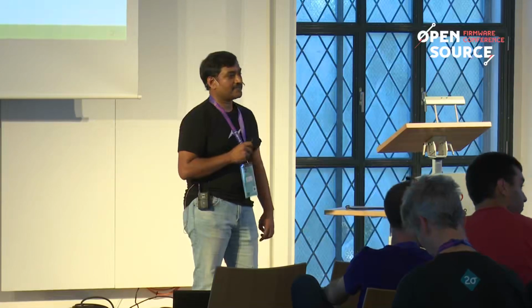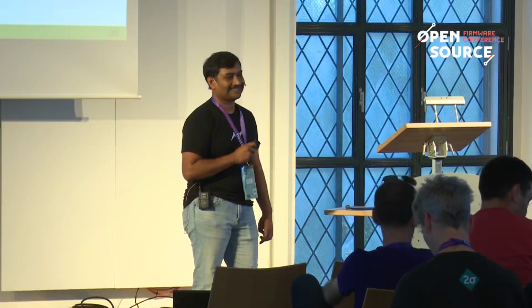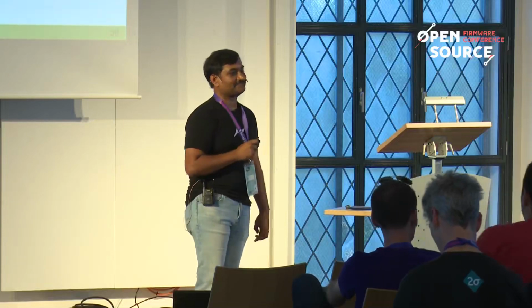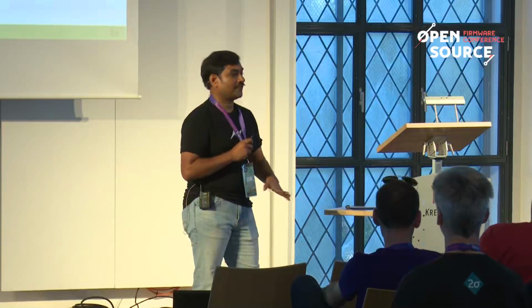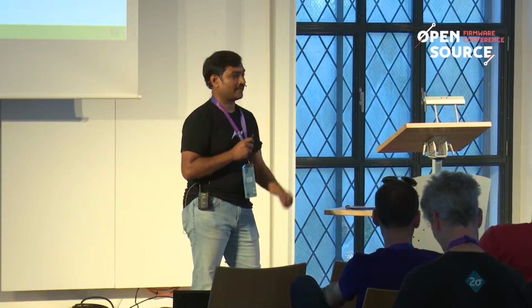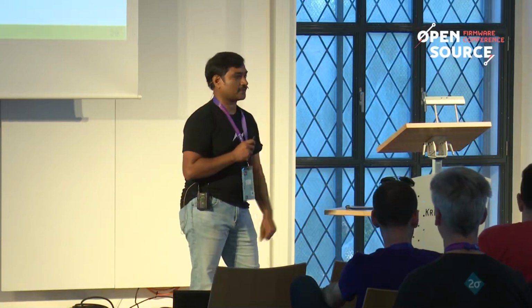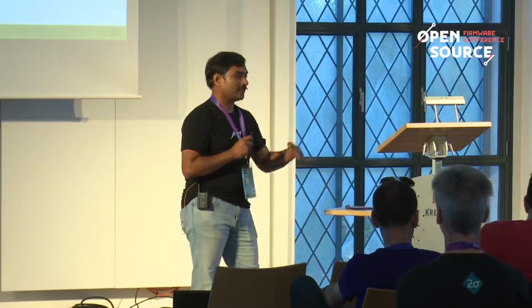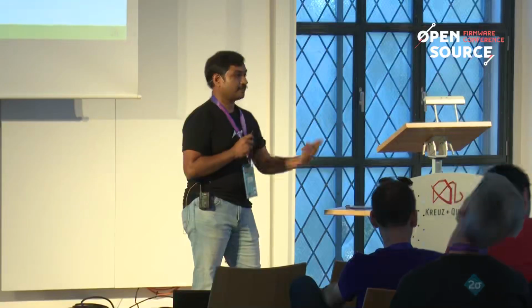Especially previously, ASpeed used to give an SDK, and you have to debug a lot. So now our ask for the next chip is that they directly contribute to Linux instead of giving us an SDK. The driver part will be directly contributed to the open source kernel, so the quality of the drivers goes up through a lot of iterations, and we can reuse the code.